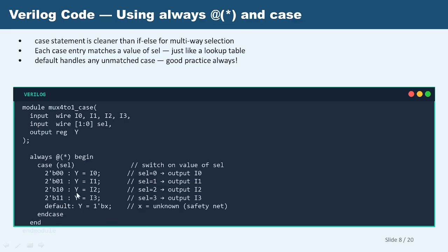When it comes to case, it is the same thing for creating a module. You need to mention reg, because you are using an always block in the design code.